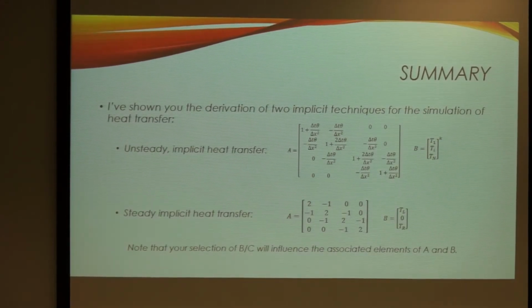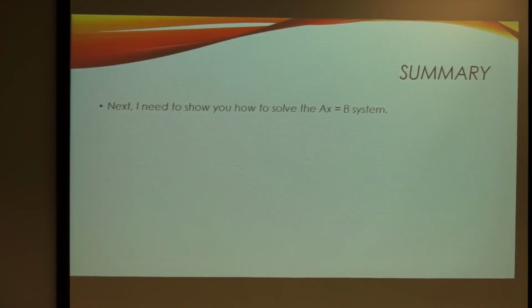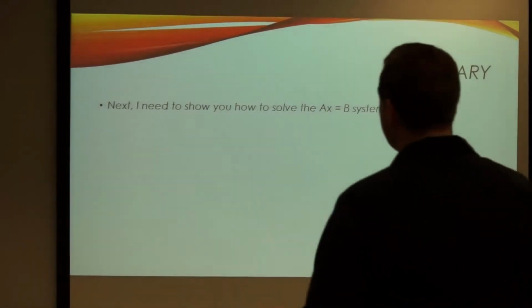You can't have 2 Neumanns for steady. So that's why sometimes people use commercial software and they build their problem and they set all of the boundaries by accident to Neumann, and then the software tells them that the matrix is singular and they don't know what it means. It's because they can't find a solution. That's why. Alright, that's the end of this part.